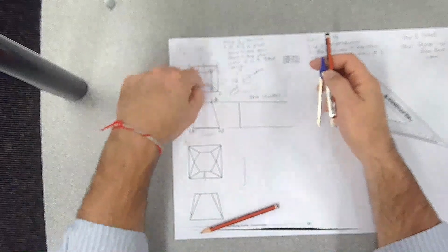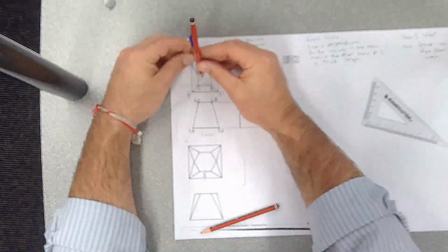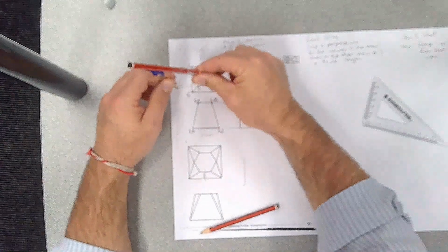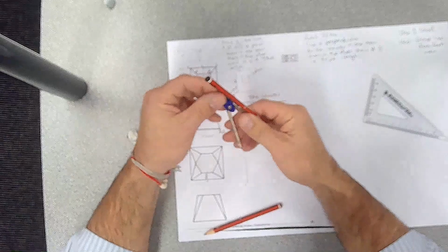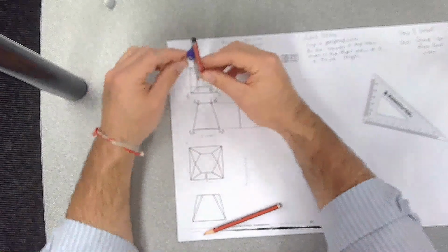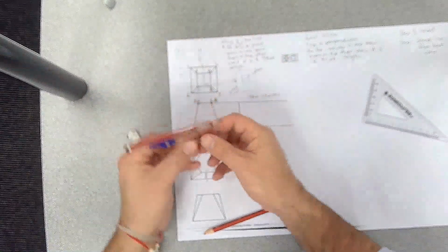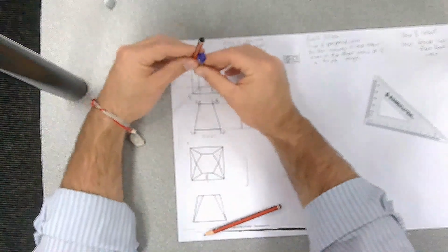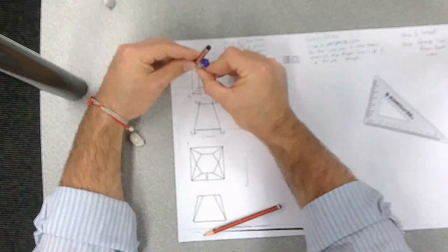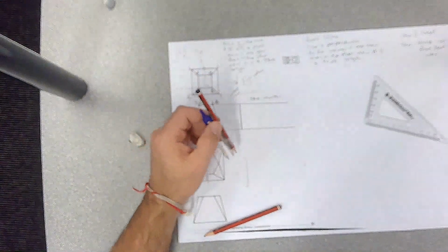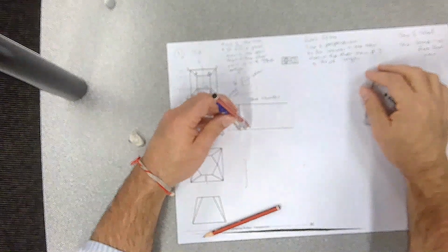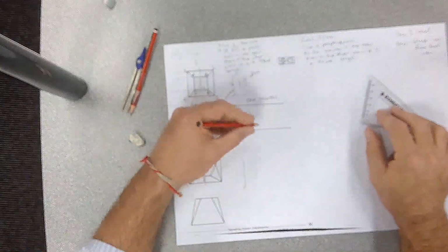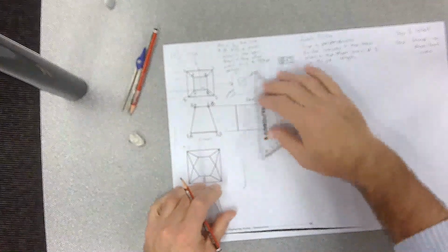You always go to the top view, you take your compass. Now if you were to go 1A and then do the swing here, you're going to get it wrong. You've got to remember that to find that true length, we go to the top view and we put our compass between the 1 and the A on this top view. So it's a way of measuring it with the compass. Then we take our trusty compass and we swing an arc here. Now we've got a point there, and that's going to give us our line